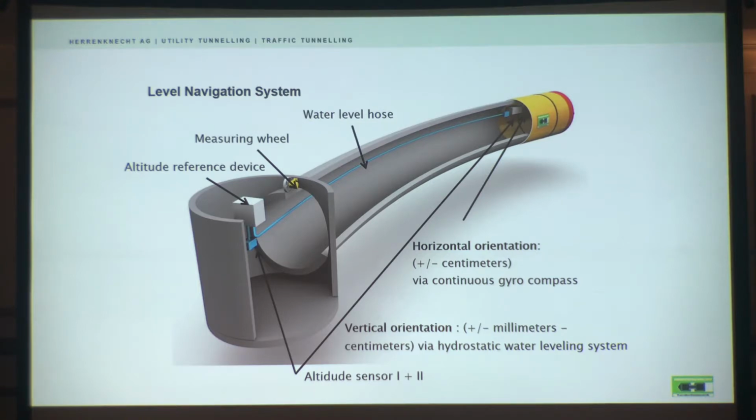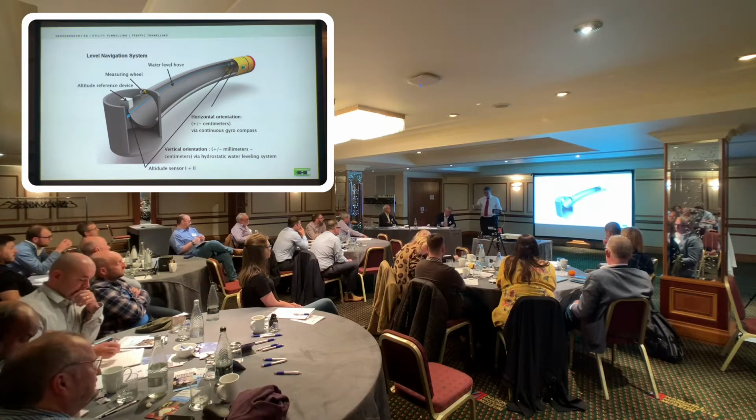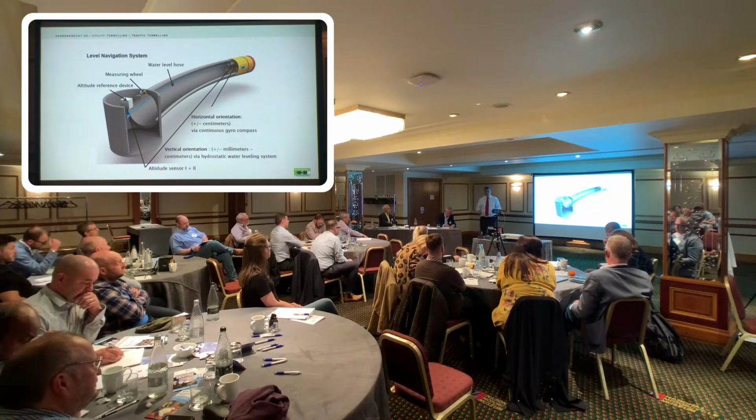So if you can design your curve, roughly speaking, if you were going to put a 4-foot pipe in, 1.2 metres, it has approximately 1.5 metre outside diameter of the pipe, you will do a radius of 150 metres. If you're going to use an 1800, that's 2.1 outside, about 200 metre radius, 2.4, etc. So roughly speaking, the outside diameter, if it's 1500 millimetres, knock a zero off, that's the kind of radius you can do with a curved pipe jack.